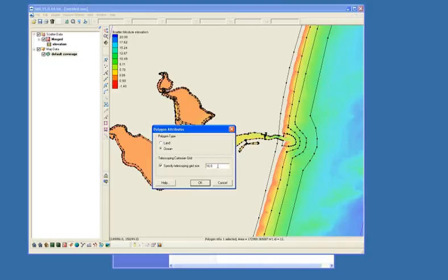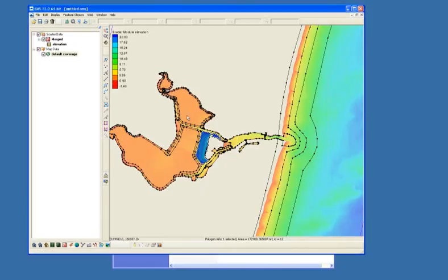Just know that the values that you specify in here could be any values you want, but what's actually going to be represented in the grid are by factors of 2. So if your largest cell size is 200 meters, well, your smallest cell size is 20 meters, then your other zones of resolution go up by a factor of 2 onto that. So it'll be 20 meters, 40 meters, 80 meters, 160 meters, etc. So you can go through and specify these each individually.